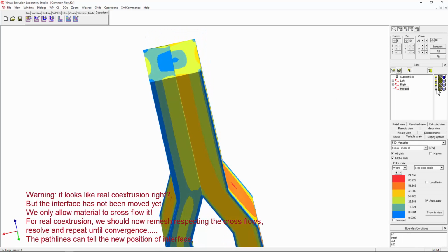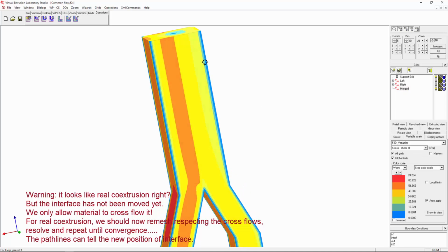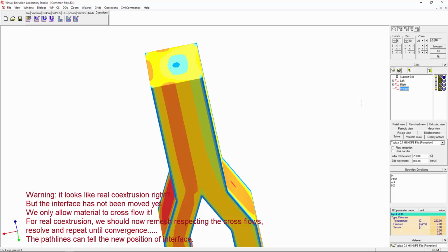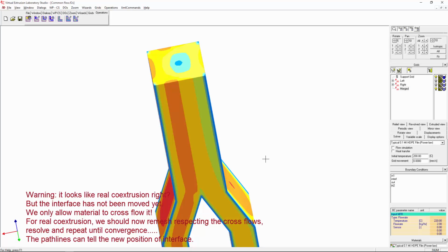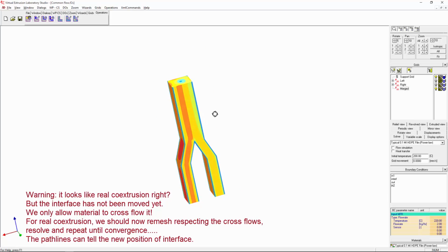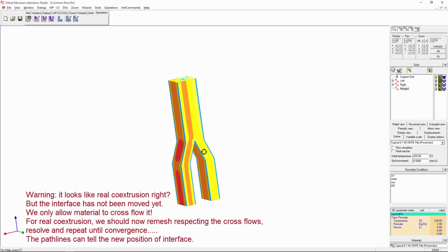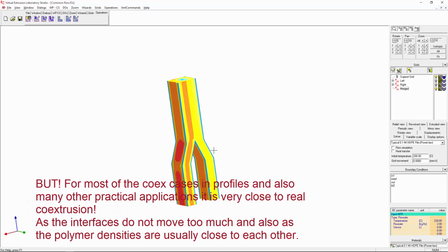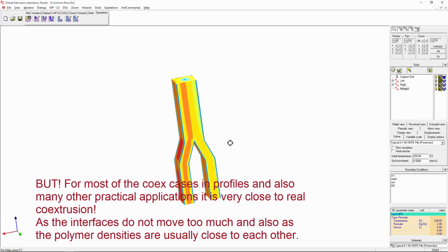But if we go to the merged one, the stresses used are calculated from HDP. They are not calculated from LDP and HDP. So the merged grid does not know in which element we have which polymer. So whatever you do in post-processing, like particle tracing, that's correct. If you do cuts and look at velocities and the pressures, that's correct. But once you try to check the stresses, or anything that is material dependent, you have to be aware that the half which was using LDP is not correct. It's using the wrong polymer.